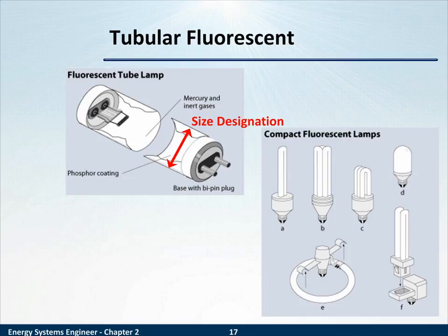It's not useful for creating light. However, you notice fluorescent lamps have a white coating on the inside. That phosphor coating inside the tube, when its electrons excite up from the impact of the ultraviolet light, when those electrons in the phosphor relax, they produce visible light. And depending on the phosphor coating, you can get different colors of fluorescent light.